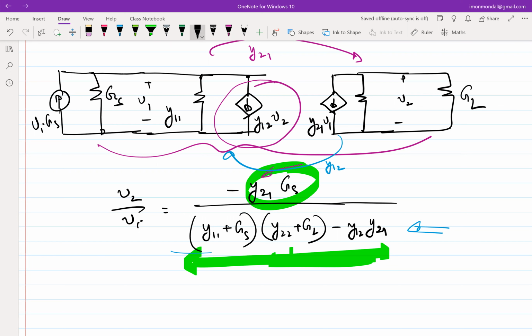Okay, fine. Now if we agree that setting this denominator to 0 is not the right thing to do if you are trying to design an amplifier, not an oscillator, then, assuming all these terms are positive, what is the fail-safe way of ensuring the denominator doesn't go to 0?